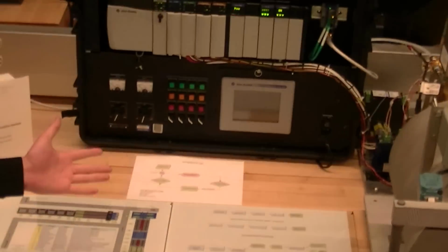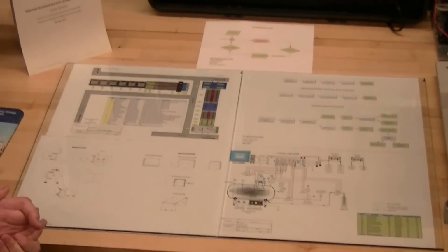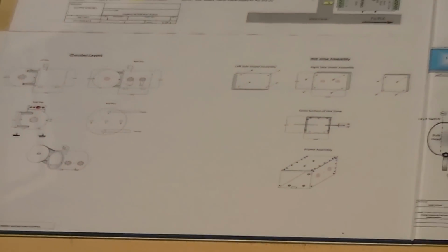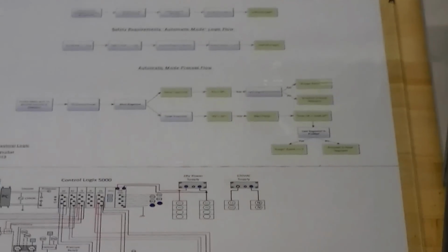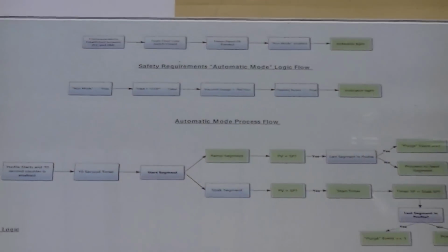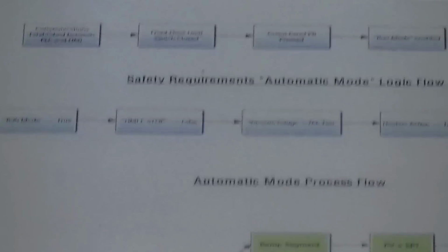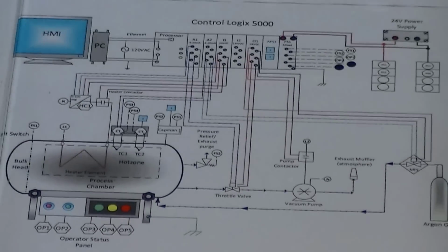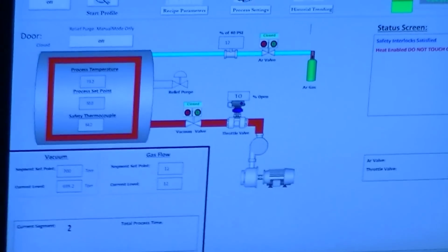Basically, it's a series of contactors and DIN rail terminal blocks that just route the appropriate control signals to the proper I/O. And we also have some additional safety on here. For example, the E-stop, if that is depressed during the cycle, it will cut out and go to a final purge cycle. There's also an emergency stop on the HMI that will actually, using a master control relay in the software, cut all outputs of the system.